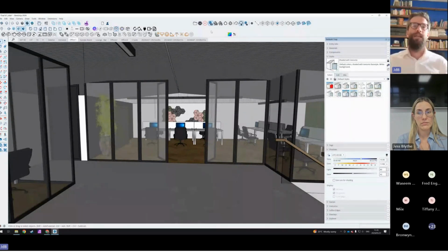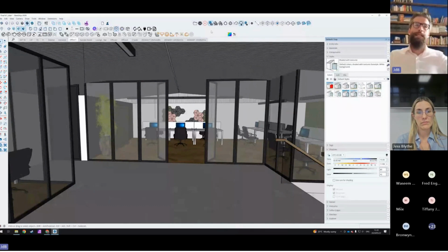Now that is great, and it will take anyone somewhere from 2 to 3 weeks of intensive training to a couple of months to systematically learn this while you're working in the office. But a great step up from the SketchUp diffusion or the ambient occlusion feature is to use V-Ray Vision. So what V-Ray Vision will do, it is this button over here, is it will load in the whole scene as if it is already being rendered. So it will be a real-time visualization. So we're going to load that in, and it will take 1 or 2 minutes to actually load all the geometry, and then we will see that real-life preview.